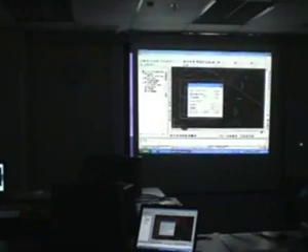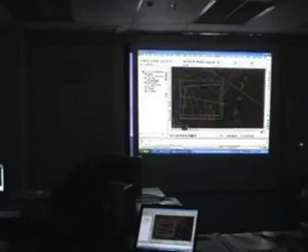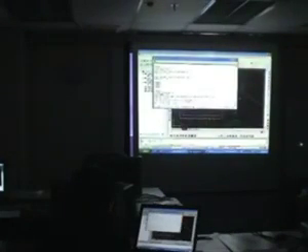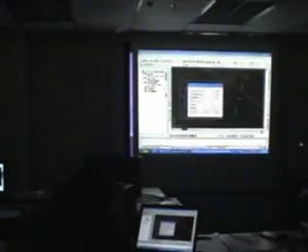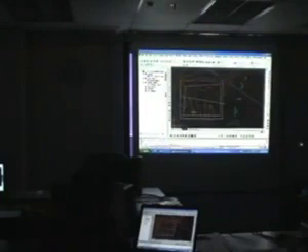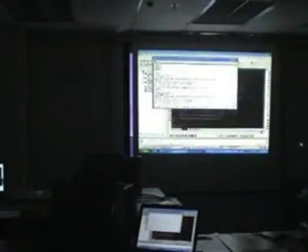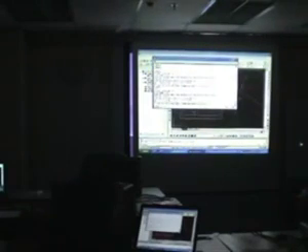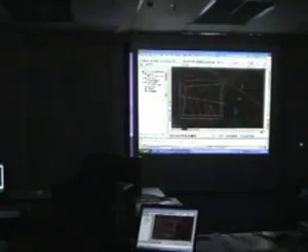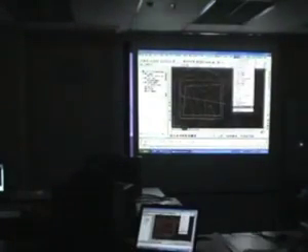One is the average end area method, and the other is the prismoidal method. These two fall under the section volume method. I'm going to set the fill factor at 1.2, and we're going to run the average end area method first. So I'll click OK. You can see at the bottom, this is the volume calculation: cut, fill, and net volume. We're going to run this one more time, now using the prismoidal method. This is the cut volume, fill volume, and our net volume. Of course, looking at it in your text window history and having to write this down is very troublesome. So what you can do is compile a summary report.